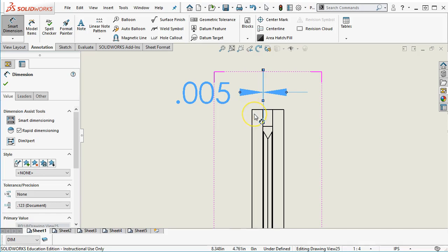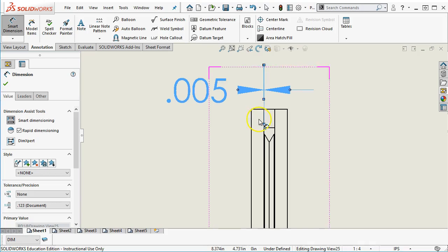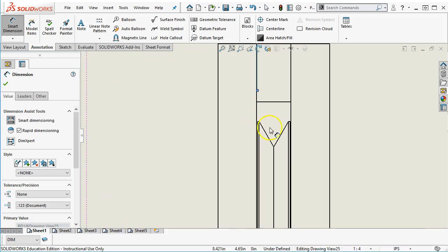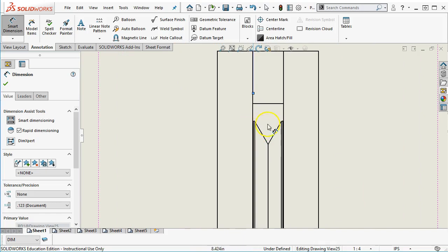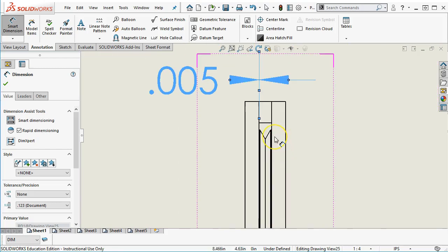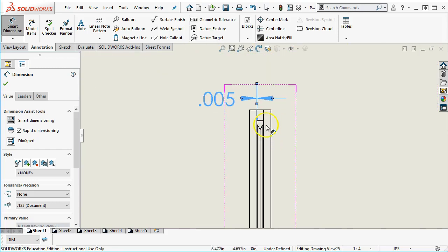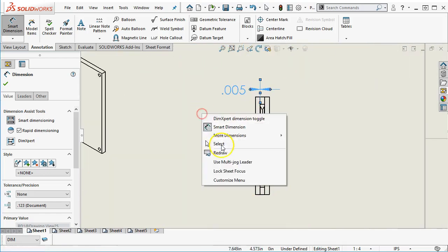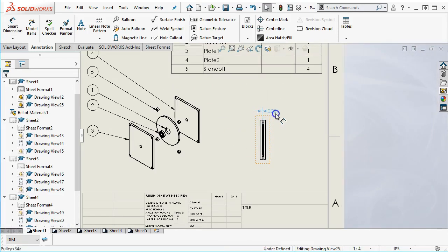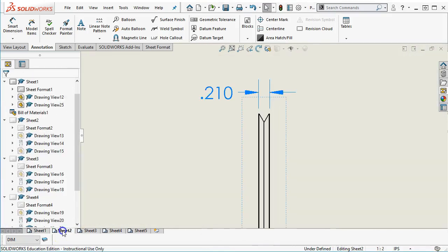7.5. All right, so pulling numbers out of my head again. All right, so if we go from 210 down to 205, I'll have 7.5 thousandths clearance on each side. And if we grow to 215, then I'll have 2.5 thousandths on each side. All right, worst case scenario, the 2.5 is more of an issue than the 7.5. All right, the other thing that's driving is the standoffs. So the standoffs just took on a whole new level of what we're going to do with those. All right, so I don't necessarily need to keep that view, but I'm going to be coming back to it for stack up.